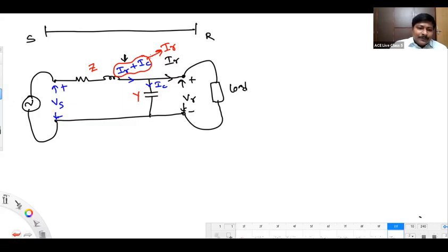The charging current is negligibly small. Even if you consider it in the circuit or remove the capacitor from the circuit, there won't be any change in the final result. So in that perspective, which is easy for you, considering the capacitor in the circuit or neglecting it, in the analysis or mathematical calculations? Removing the capacitor will be easy.